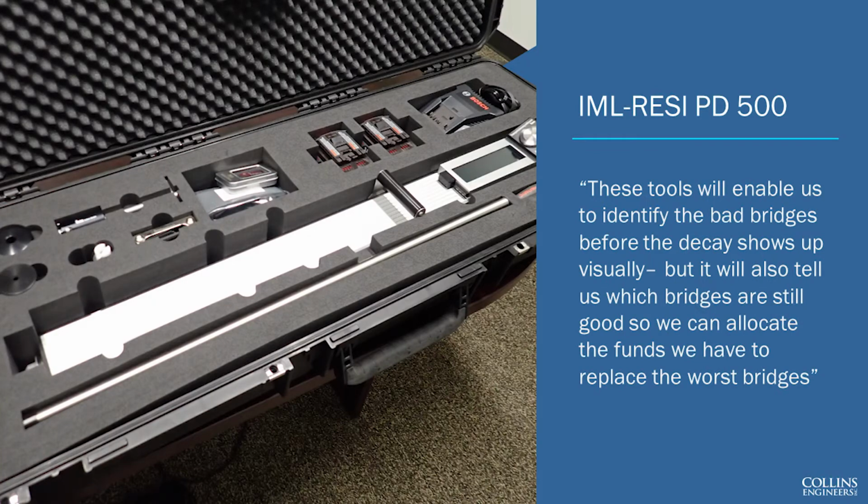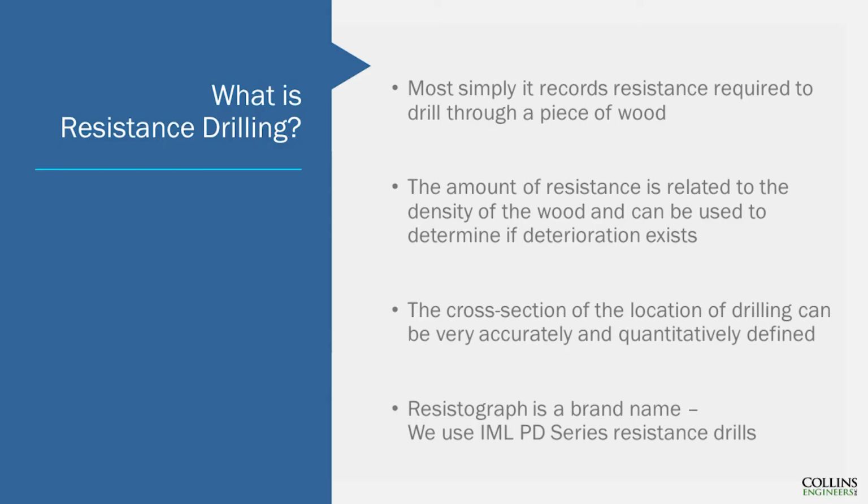Resistograph's the brand name. This allows you to put a number to the less quantitative data, the kind of things that we talked about earlier. Simply put, it's a drill that records digitally the resistance required to drill through a piece of wood. The resistance is related to the density. Basically, it's very accurate, very quantitative, basically the exact opposite of the old inspection methods of yesteryear.